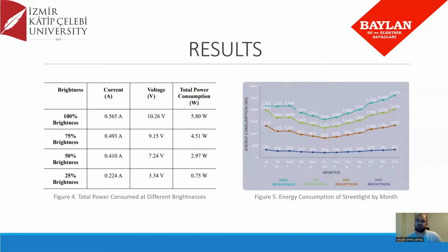When the system starts, it sends the time request command to the server to get the local time. If the local time does not reach the system, the command is repeated at certain time intervals. When the local time reaches the processor, it controls when the LED street light will turn on according to the mode and day. When the LED street light is on, it lights up at 100% brightness. At the same time, the motion sensor and LDR sensor start to measure. When the light intensity falls below a specific value, the street light sends information through the LoRa terminal device to the server that the street light is malfunctioning.